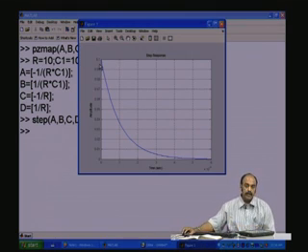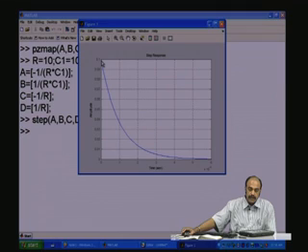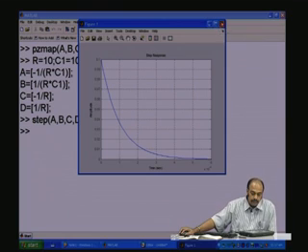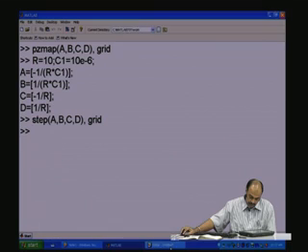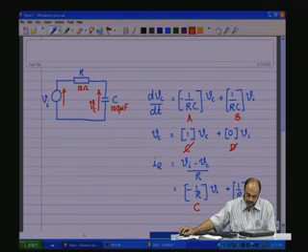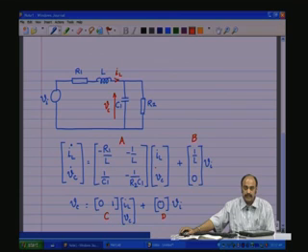So, you see the current, initially there is a high current because there is a step which is a high frequency, capacitor acts as a short, V by R. Initially there is no voltage across C, the whole voltage appears across R. So, 1 divided by 10 ohms, 0.1 amps, and that starts exponentially decaying to 0 as the capacitor charges to full voltage. This is the nature of the current waveform through. So, as I was saying, you can see whatever output you want to see. Now, coming back to the circuit of interest, which is the LC circuit.